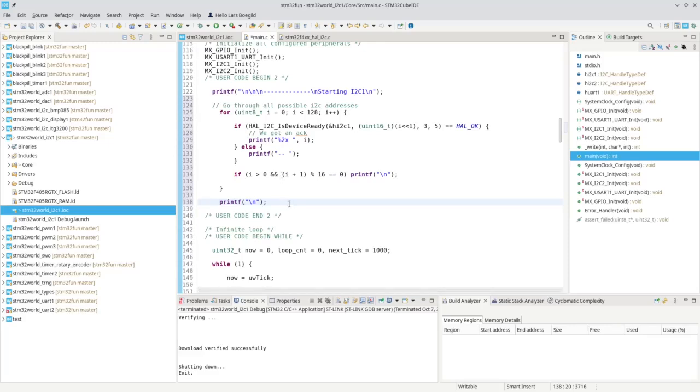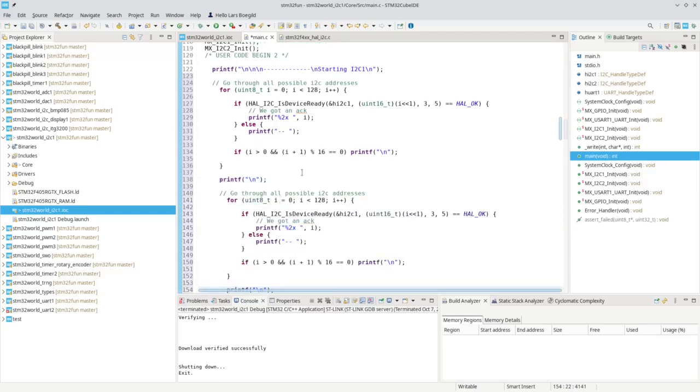So we'll do this scan of one, and then we'll scan one more time. I wrote it in capital, so let me fix that, I2C 2. So we'll scan both buses. In the first example, we'll scan I2C 1, and down here we will scan bus 2.